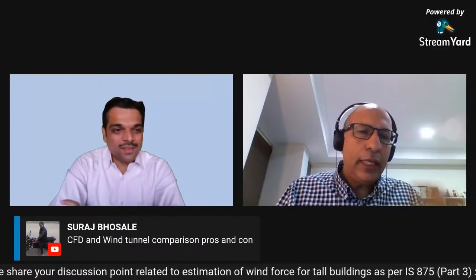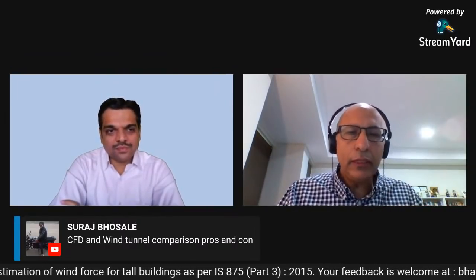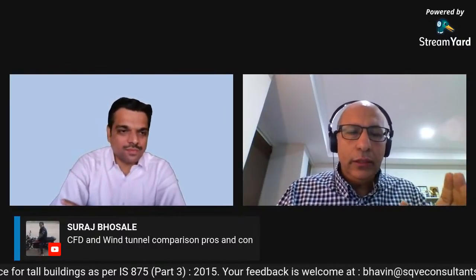You wouldn't go alone on CFD. But there are applications for CFD in tall buildings where obviously wind tunnel can't go, such as looking at stack effects, environmental, like thermal comfort in semi-open spaces, in an open area, a common area in a podium of a tall building, for example.